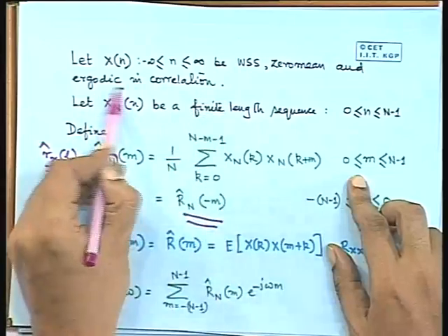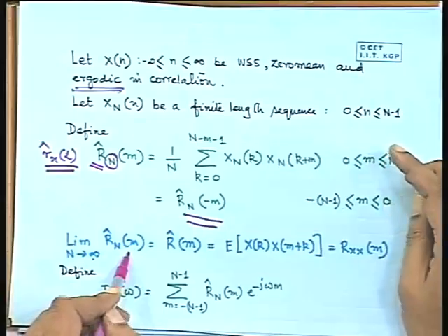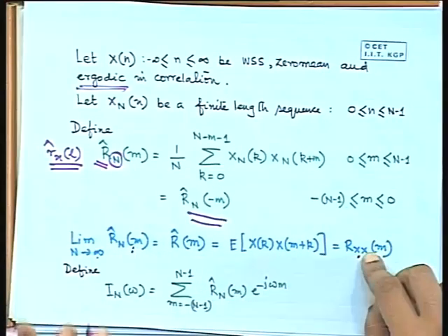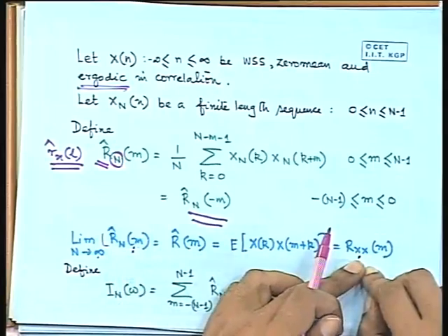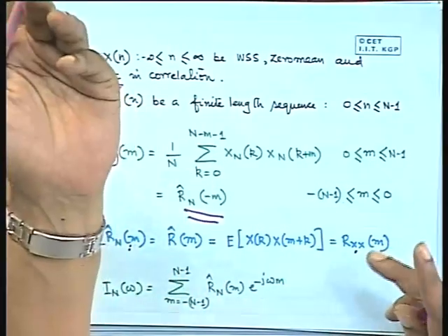See, I have not taken expectation, I have just taken n tending to infinity, because I have assumed that the process is ergodic. So if the process is ergodic, then time average is equal to ensemble average by assumption. So this long time average will converge on the ensemble average. So therefore this will be equal to this. If I take an expectation of this, it will obviously match here, whether it is ergodic or not, but I have not taken expectation. Because taking expectation is of no use to me. I want to calculate based on one realization. Previously I took expectation just to show a property, but now I want to compute, so I cannot take an ensemble average. I only want to stay in the time domain, only time averages I can use.